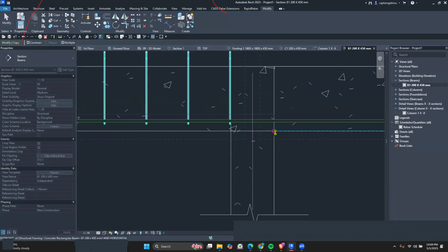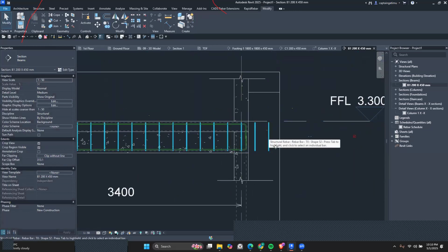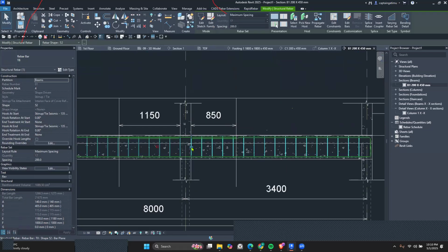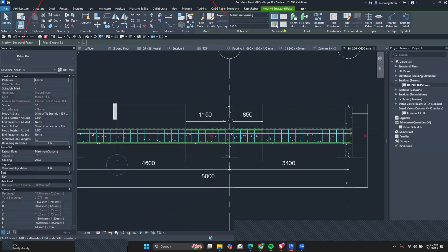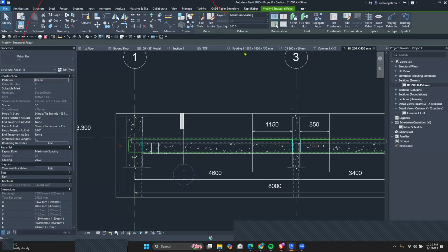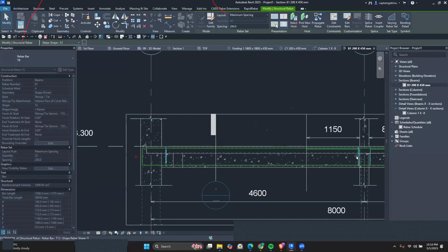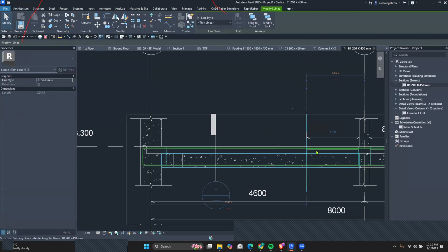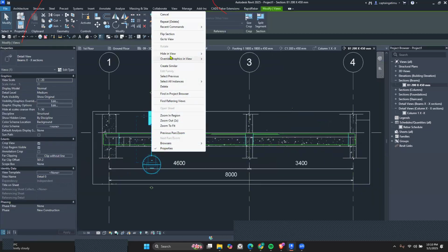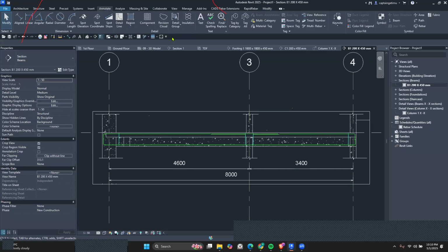After you have that, now you can end it here, and then click on escape and expand them more automatically. Okay, then after you have that, presentation first and last, presentation first and last, and you are good to go. We no longer need these detail lines, so we can just delete them and hide this in view. Okay, so with that, you can quickly annotate it.